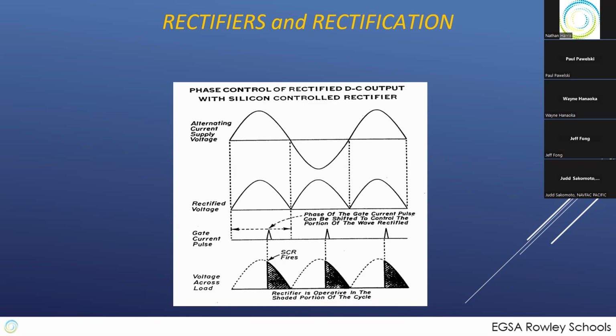Now, older generator systems, and in some of the locations that you're at, you will find older Cat 3600s, the MTU equivalent or the Cummins equivalent of them. They have control systems that work with relays, thyristors, and Zener diodes. And the way that ends up working is you've got a sensor reading something, temperature or voltage or whatever, and it's being used to charge up a capacitor. When that capacitor gets to a certain voltage, then a Zener diode dumps it. That's being used to create the gate pulse current.